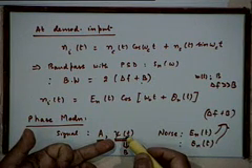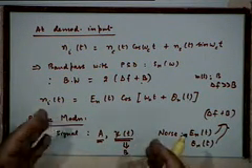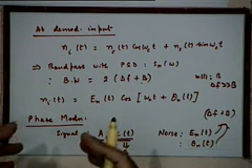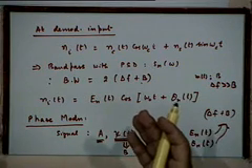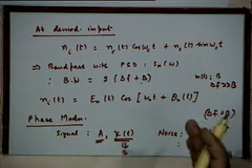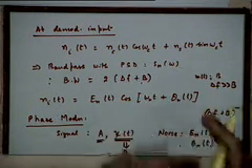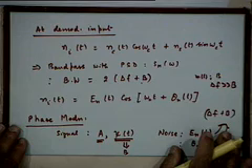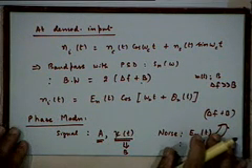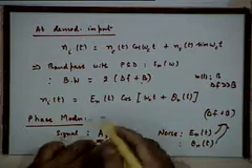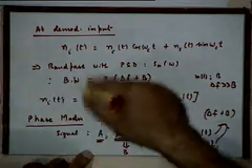That means you can think of the phase of the carrier which contains the message as more or less remaining constant over several cycles, whereas the corresponding phase of the noise would have undergone very wild fluctuations in that period. Over a small period of time, the value of psi of t is nearly constant. The carrier goes through many cycles, and over many cycles of the carrier, the value of psi of t is nearly constant, equal to some kp times m(t).